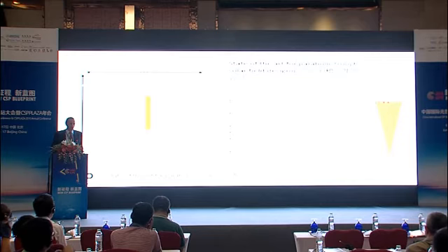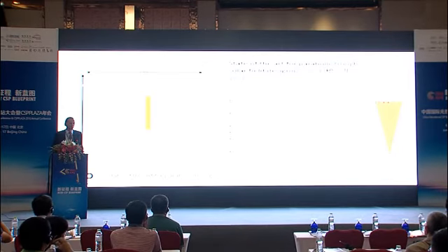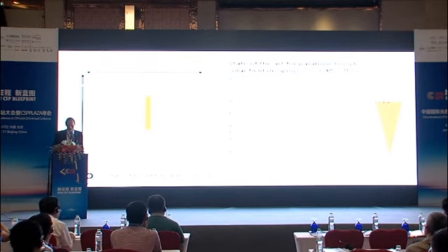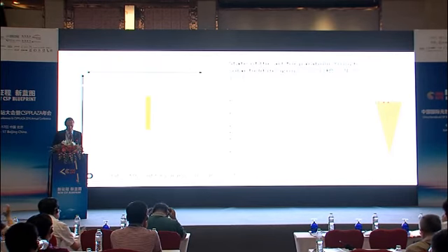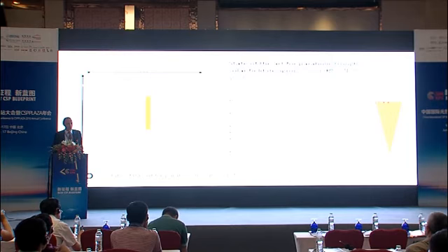So this is more or less my personal view. The ones at the top are quite good and they should be kept, and they help to reduce the cost. But the orientation of the solar field north to south and the collector on leveled ground is actually quite questionable because it has a cost effect. On the north-south layout, there are some sites where you're constrained by the boundaries, and they have nothing to do with north-south.